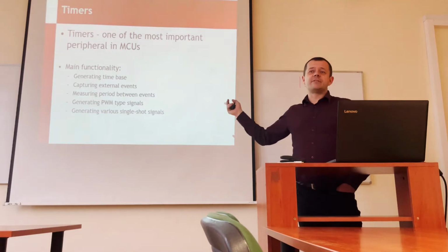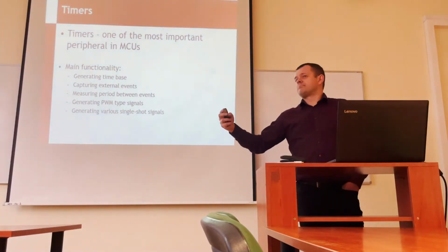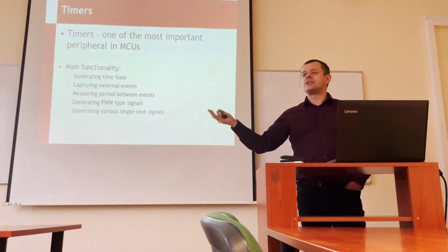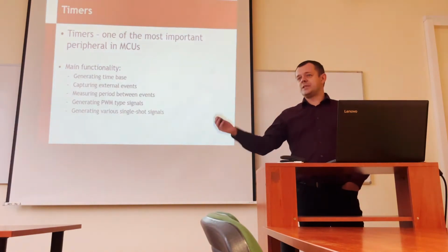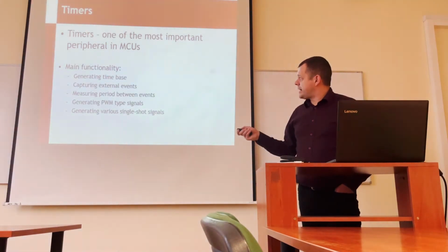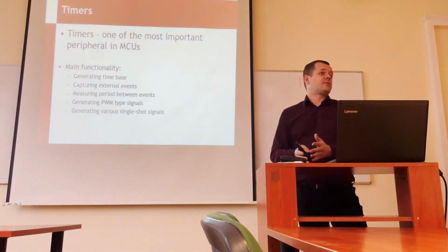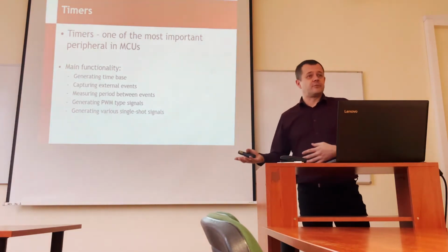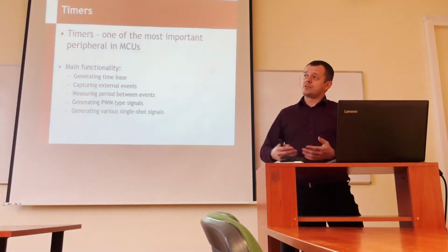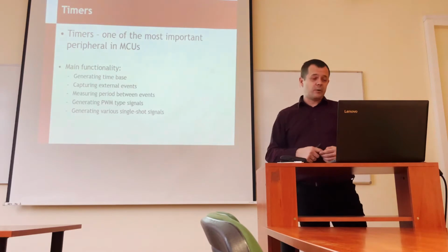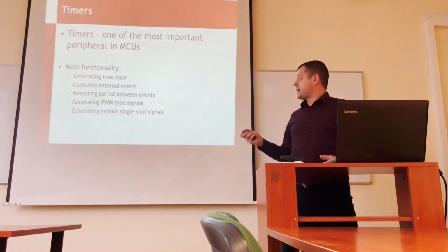They can be events coming from the external world, for example the state of a pin is changed, or some communication started. But it can also be capturing when some peripheral finished an operation, so we can measure the time of an operation on some other peripheral. Some communication started or finished and we want to measure how much time it took, we can capture this.